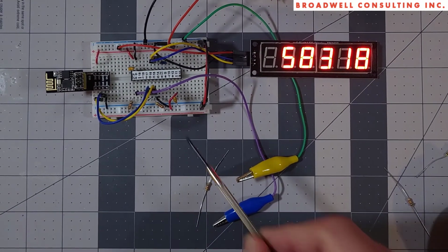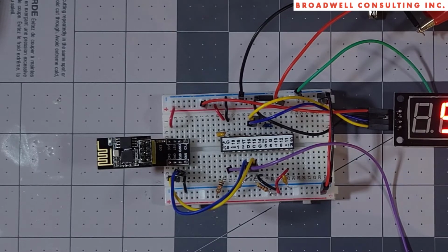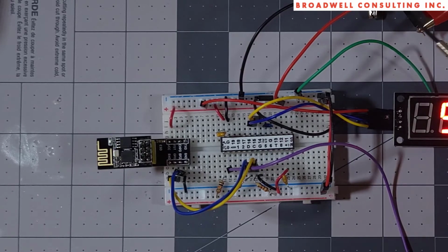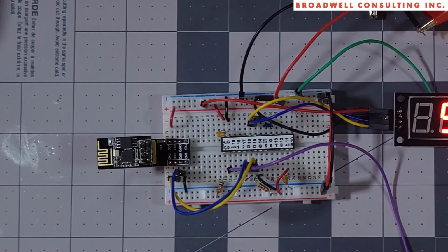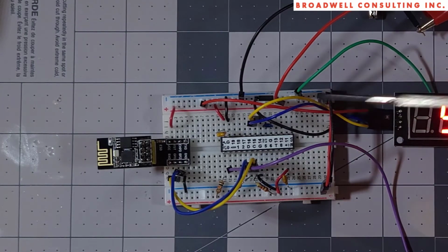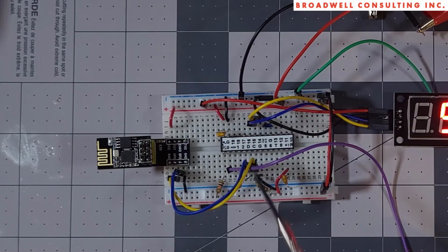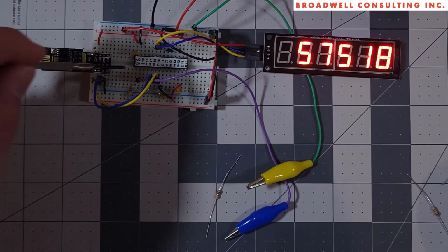Here we can see our circuit. We have the Serial Wombat chip with all of the support components, the 3 capacitors, the pull-up on reset. We're getting our power from an external 3.3 volt power supply coming into the breadboard. The whole thing's being driven by an ESP01 with its I2C lines tied up to the Serial Wombat chip. We've got a TM1637 display being driven by the Serial Wombat chip. And I've got 2 alligator clips here, one of which is tied to ground, one of which is tied to pin 0 to match up with the sketch that we showed earlier.